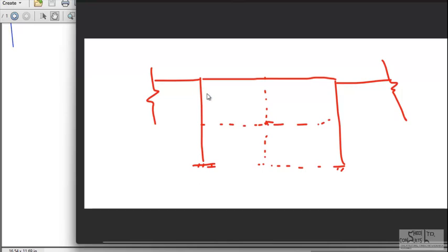The total force, right, is the wind pressure times the windage area. So the equivalent static wind pressure times the area will give the total force. That divided by 4 will give you the loading on the joints for closed windage area, for closed structures. Okay, for open structures, the wind load will be applied on the stanchions as distributed loads.